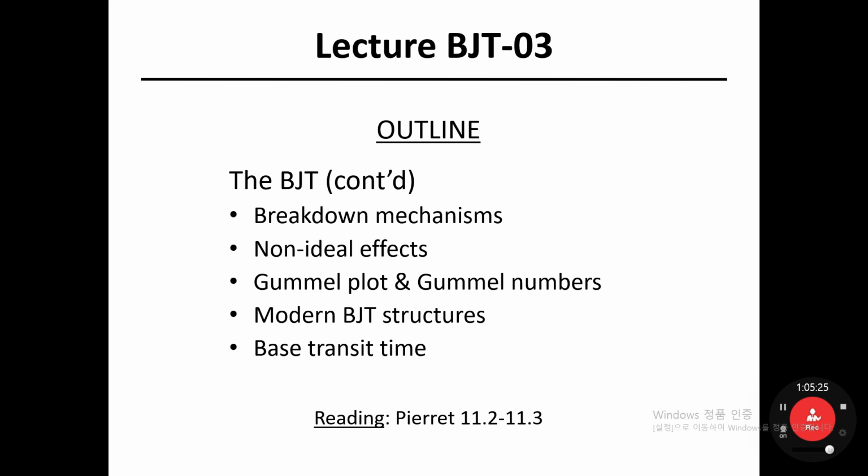So people in industry adopted planar bulk MOSFET because it is good at suppressing power consumption. And even on top of that, the chip area, the layout area, for a MOSFET is much smaller than the layout area of a single BJT on the silicon substrate.